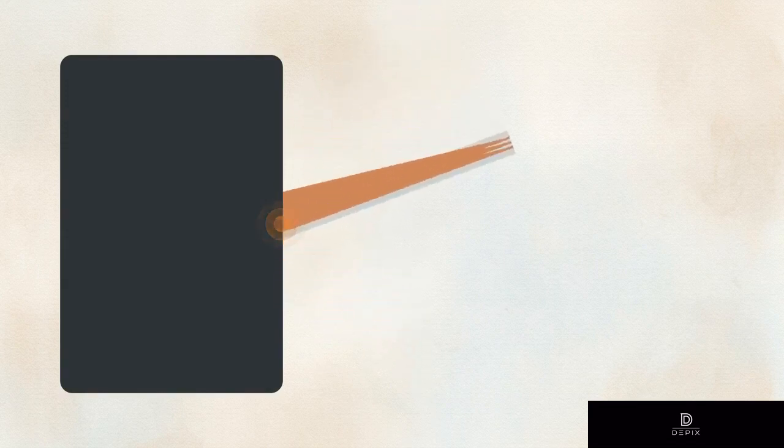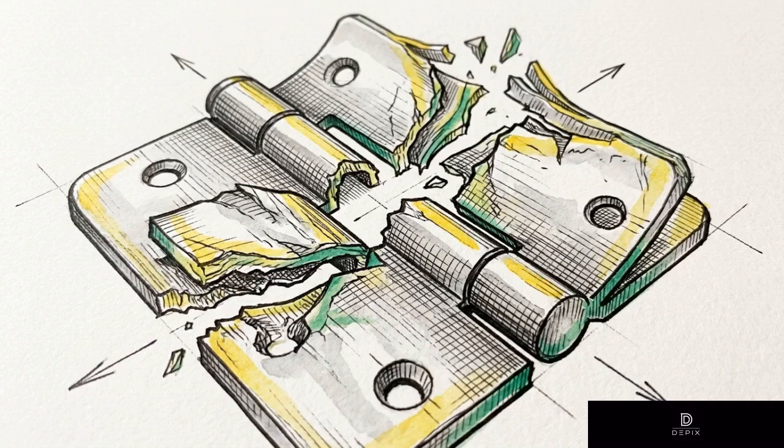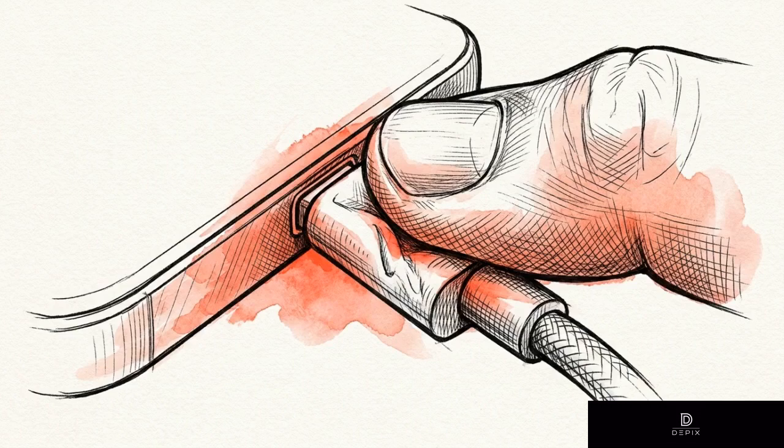You have a completely flexible object colliding abruptly with a completely rigid housing. Without a mechanical gradient between the two, a sudden transition concentrates every bending cycle into one single microscopic line of copper strands. That gradient is called strain relief. When engineered correctly, the cable curves away in one easy arc. When it is ignored, you have built a hinge with no pivot, placing maximum stress on a spot the user will flex 1,000 times a year.